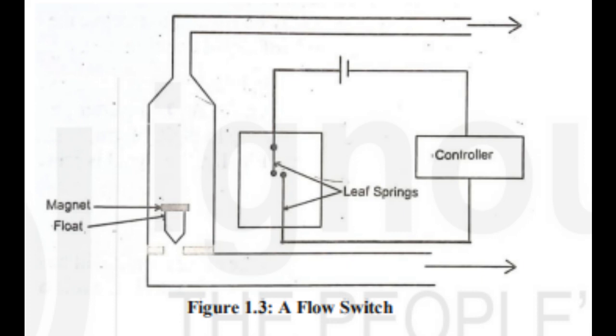1.5.1 Components of a continuous sensing system. The components of a sensing system and their relationship to a digital controller are shown in Figure 1.4. Each component of the chain has a unique purpose, which shall be briefly explained. The sensor takes the actual physical input, such as force or temperature, and provides an output that can be used by an electronic measurement circuit. The measurement circuit is used for calibration and reading of the sensor output.